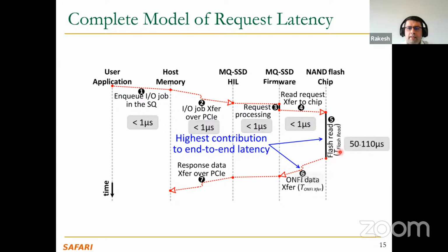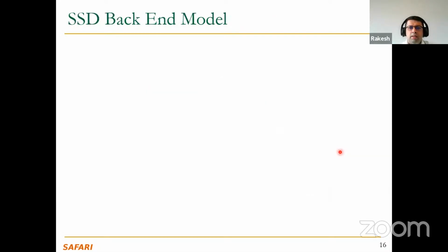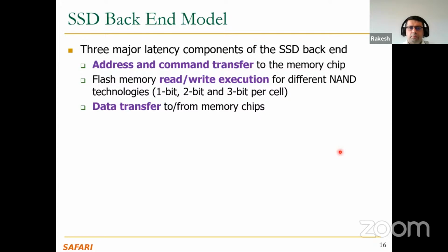So we see that the actual flash read and the data transfer from the NAND flash chip to the firmware or the SSD controller takes a substantial amount of time, and all these latencies are modeled in MQSim currently. So let's look at the SSD Back End Model.